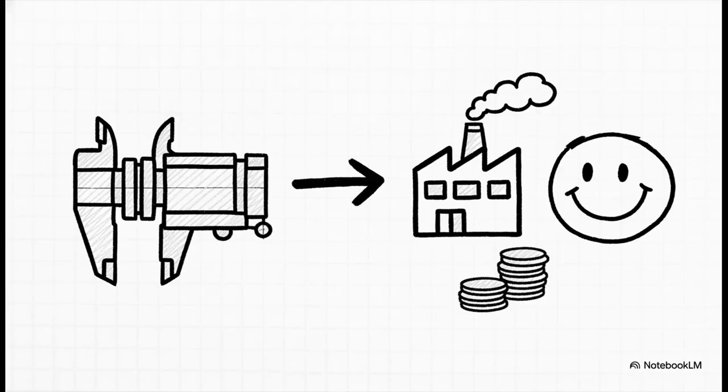The golden rule is this: GD&T should yield a cheaper part and a happier manufacturer. Period. Ultimately, applying proper position controls should clarify your design intent, simplify the inspection process, and lead to much more cost-effective manufacturing. It should absolutely not add unnecessary complexity or drive up your scrap rates.